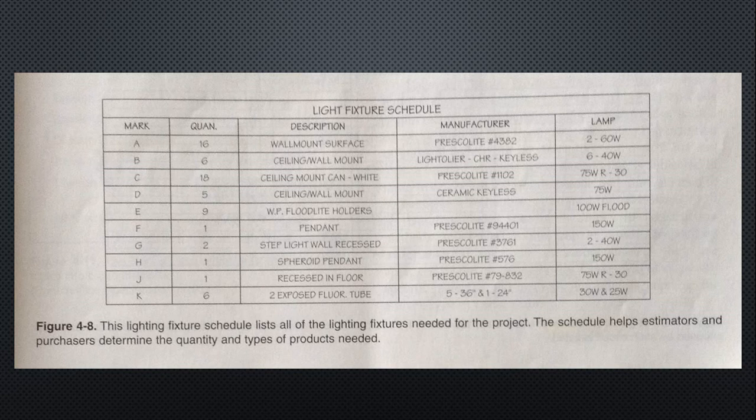Equipment schedule. An equipment schedule lists the large electrical equipment being installed. The information provided in this schedule varies depending on the specific type of equipment listed. Equipment schedules may include the voltage provided to the equipment, size and type of overcurrent protection, and the number and sizes of conductors feeding the equipment. Motors, heating units, and cooling units are often listed in equipment schedules.